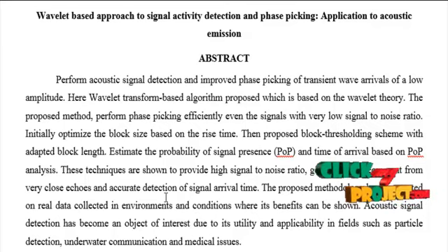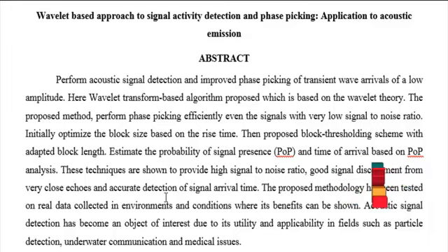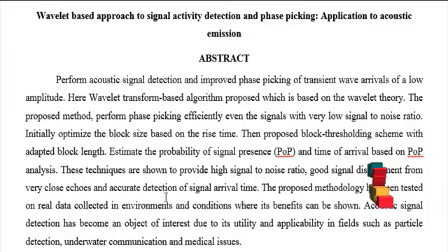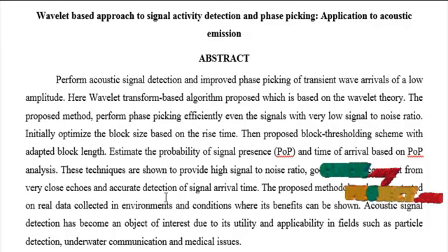Acoustic signal detection has become an object of interest due to its utility and applicability in fields such as particle detection, underwater communication, and medical issues. The probability that a given coefficient contains a significant noise component is estimated assuming a generalized Laplacian prior for noise-free subband data and additive white Gaussian noise.